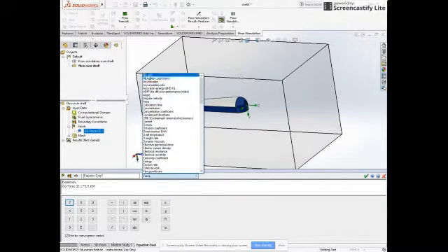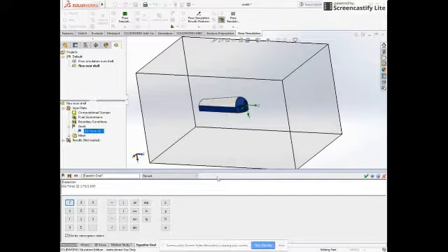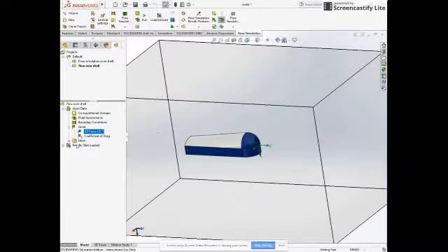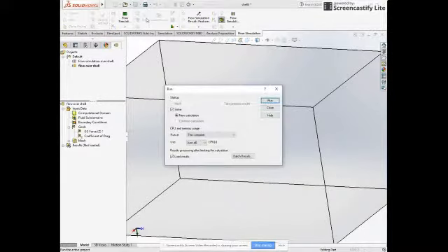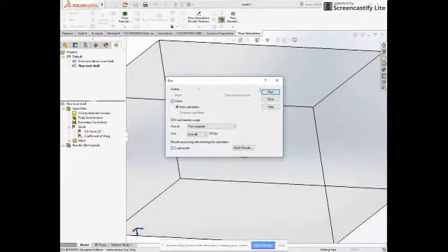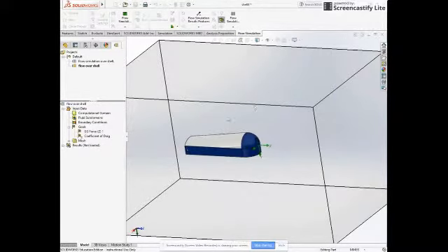And we're going to want to set this to unitless, so we'll do that and hit the green check mark. You can also set what your equation is looking for. We got the coefficient of drag. So what we're going to want to do here is run the study. There's nothing you need to do in this window. You'll just go ahead and click Run.